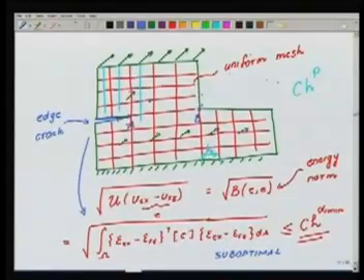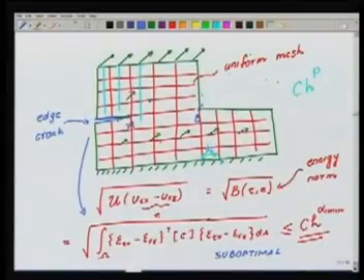So in order to get a good finite element solution, you have to refine the mesh a lot, which means a mesh with which I may not be able to compute at all, because the number of unknowns will be so high that it will be impossible for my computer to handle that many unknowns. The next question that people say is, well, I'm not interested in what is happening here. I'm interested in a region far away from any of these points, either from the crack or from the reentrant corner.